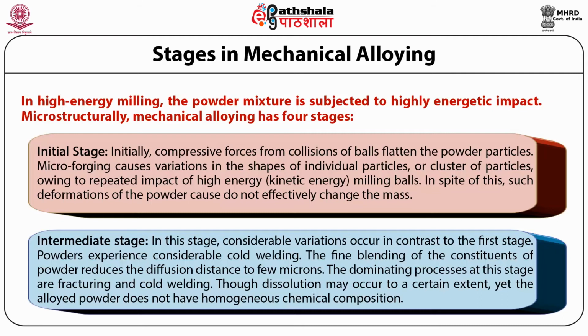The dominating processes at this stage are fracturing and cold welding. Though dissolution may occur to a certain extent, yet the alloyed powder does not have homogeneous chemical composition.